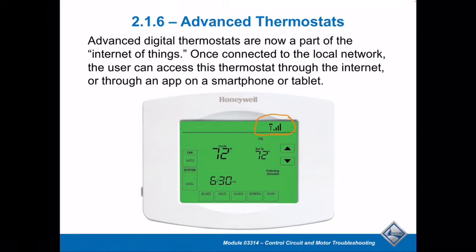Some additional features that are really advantageous on a lot of these thermostats include things like battery backup. In other words, once you program it and the power goes out, you're not going to wipe out the whole thing. Some of them might even have a double EEPROM where it holds everything, or they might use a capacitor to provide a power source for doing that.